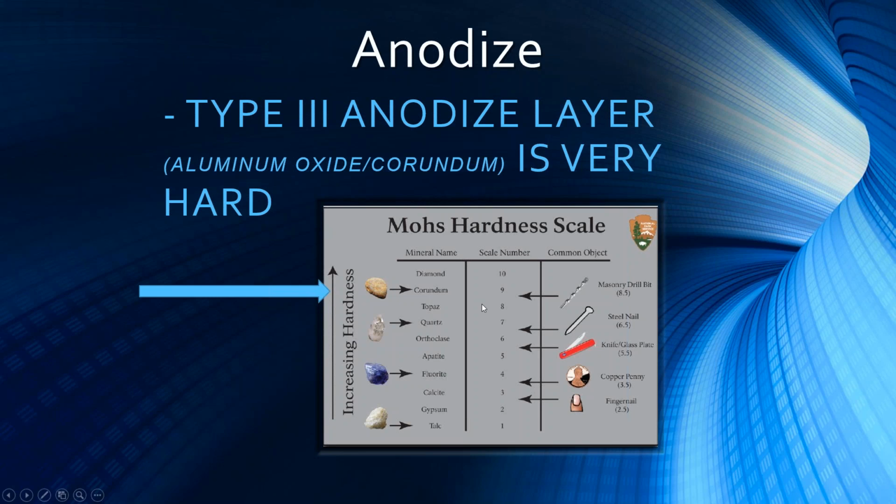And yes, Ken, let me just throw something in. This is normally considered type 3 hard anodizing. So there's type 2 and type 3, and type 2 doesn't build up. It just goes in. Type 3 does what you say. It builds up and goes in. So what we're applying is called type 3 hard anodizing. Terrific. Thank you for that clarification.